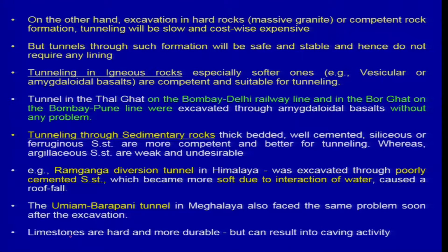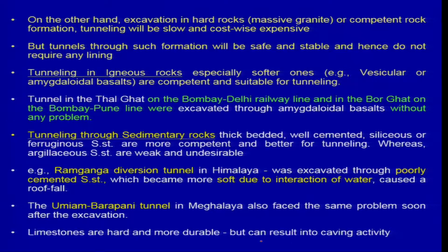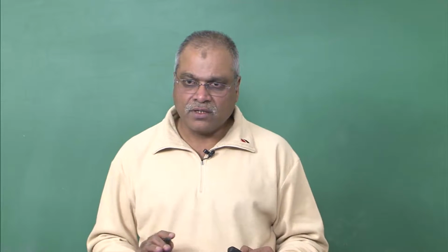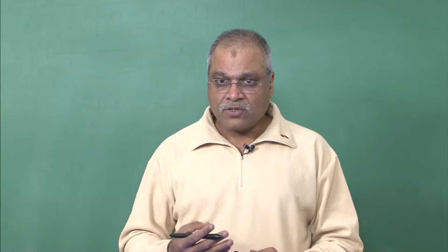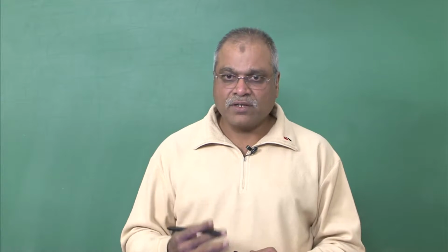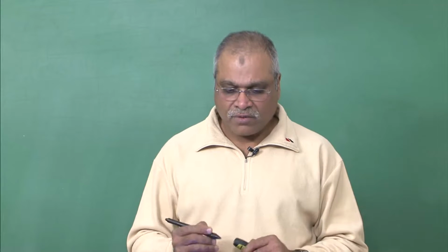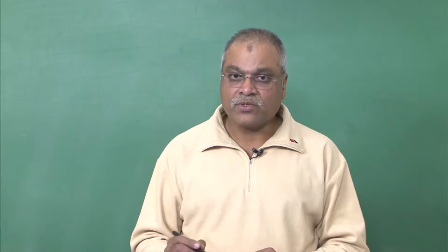And we have commonly observed that limestone, because the basic composition is mostly calcium carbonate, will react with water, and because of the dissolution activity you may face problems of caving in the subsurface. On the surface you will see it is fine, it is good, but in the subsurface there will be dissolution activity and formation of cavities. So you have a hollow portion at the base and a structure on top, which will result in the formation of sinkholes and it will collapse. So this is another problem in terms of limestone. Again, limestone is a sedimentary rock.